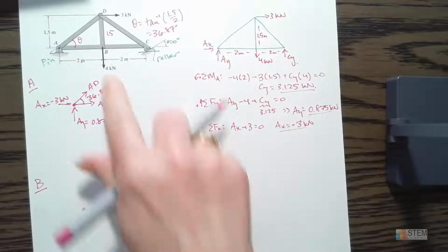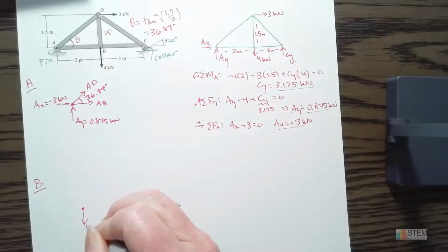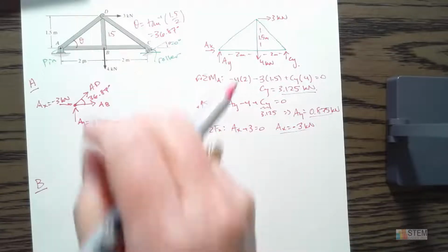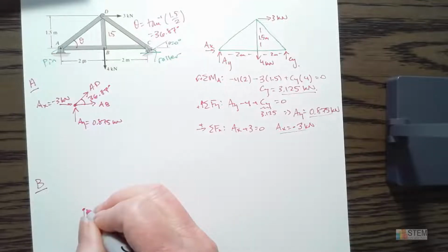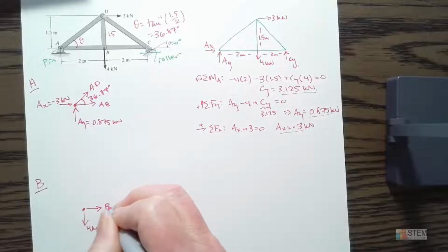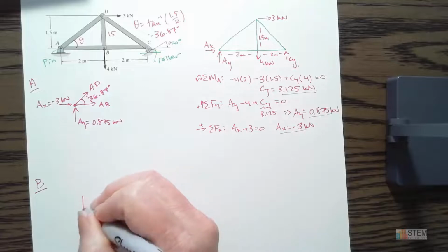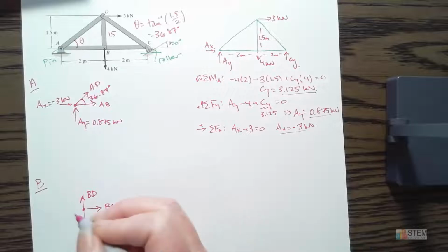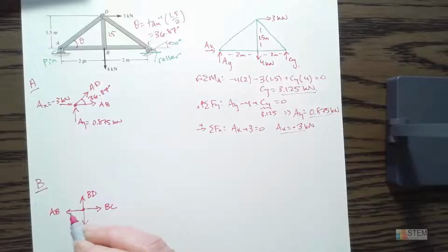All right, so point B right here, joint B. So let's draw all the external forces we have. So we got that 4 kilonewtons. And now I've got 3 members attached. All right, well, those 3 members are providing a force on this joint, so we need to represent those. Again, I'm going to put them all going out of the joint. So we got this one here, which is BC. So it's going to the right to go out of the joint. We've got BD going up. That way it's going out of the joint. And then finally, we've got this one, which is AB. That's going to the left, so it goes out of the joint.